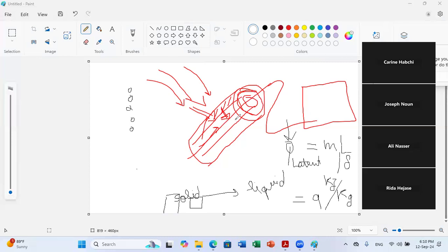Here you will try to reduce resistance, the opposite of the envelope. In the envelope of your building, you need to protect your inner environment, so you need to increase the resistance to heat flux. While in heat exchanger applications, it's exactly the opposite. You need to absorb the maximum energy from the outer environment. So you need to select material with good conduction properties.